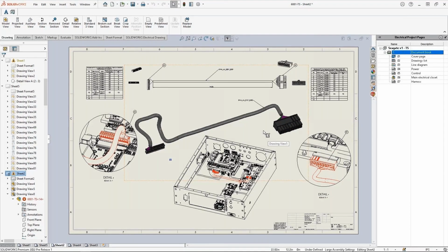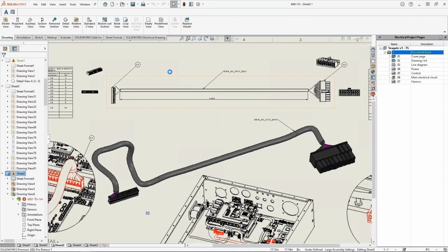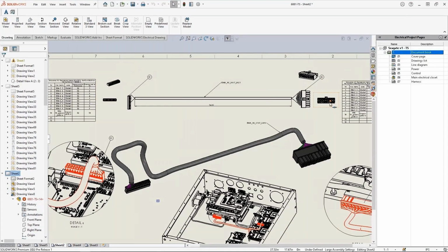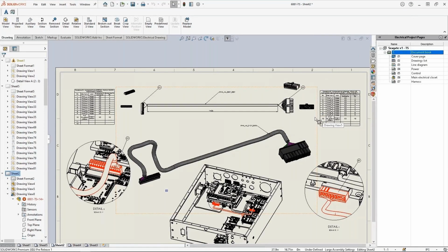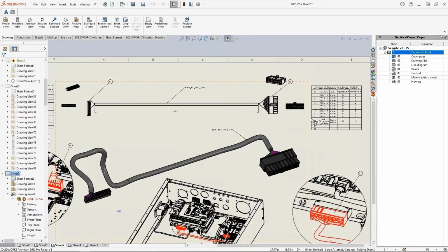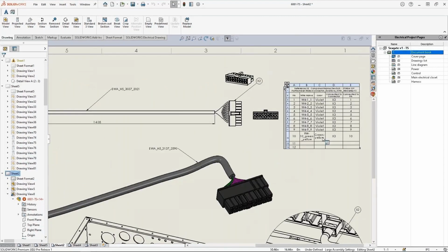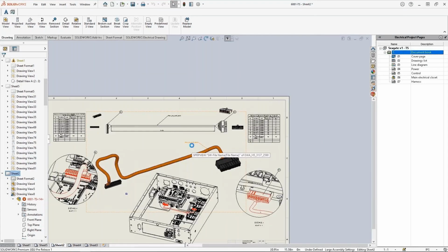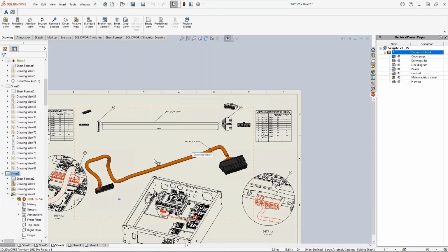Again, I just have varying views. I just threw things out here just to show the flexibility of it. But here with this center detailed view that's shaded, I can get some nice color and understand its orientation. Here I was easily able to create a flattened route for this and bring that flattened route into this drawing. So again, in an associative environment, I got detailed connector views driven by the models of those connectors, etc. Again, the benefits of a full associative environment. Here you're seeing my connection labels, again calling out, easily articulating that this is related to X2. You can see the BOM information.